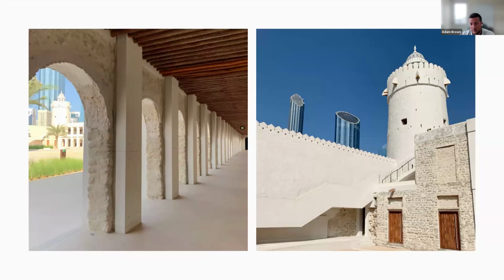Also, on many of the watchtowers, they'd started to notice massive degradation within the render and the plaster coatings. So they wanted to return that to a historically accurate coating. As such, we were tasked with creating a blend that included lime and hydrate, burnt charcoals, wood chips, and aggregates. This was based on mortar analysis within our lab, but we also had to research and review historical records. So the mortar had to match the physical, mechanical, and aesthetic performance that was found originally.